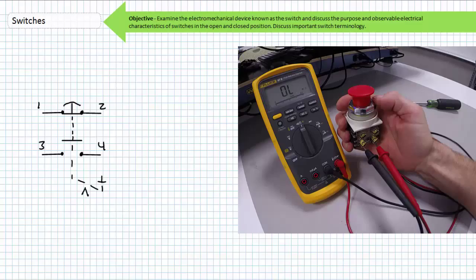This is what the dashed line modifier in the schematic means. The top portion is the mechanical interlock between the normally closed and normally open switches. This bottom portion is the maintained contact portion and indicates that it must be reset.